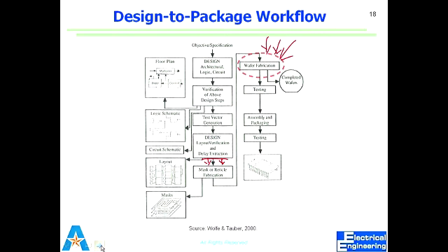So once that is verified, they result in what you call a mask or reticle. Same thing, slight difference between mask and reticle. We'll look at that: what is a reticle, what is a mask? But we generally call these things masks. So this mask is a physical representation of this layout, which was on the computer screen.